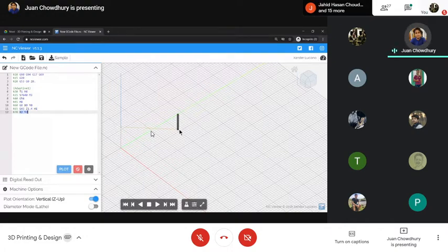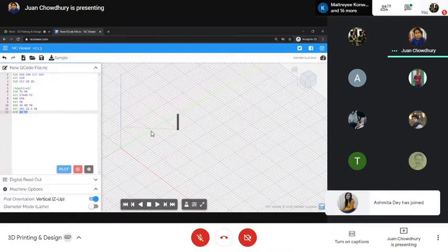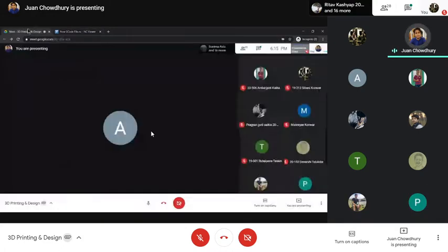Say at this moment of time, you want to start the extrusion process. You will write an M code for it. That starts the extruder. So that's how the commands differ from a G or an M. Is that part clear?